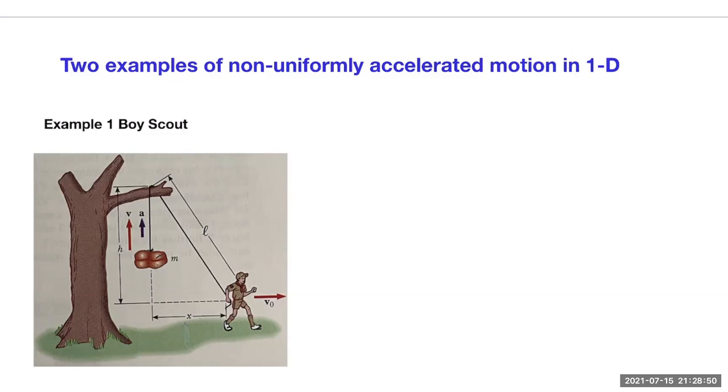Does L increase uniformly? Not quite. You see, it's not quite the case. x does increase uniformly. Okay, x is the horizontal distance measured from the package. That does increase uniformly, but L does not. And the thing is, when L increases, the package will go up because the entire length of the rope is fixed. That is very important in our analysis. Let's say the entire length of the rope is, say, 4 meters. All right, and out of that, L is equal to 3 meters, and the vertical part of the rope is 1 meter at some point.